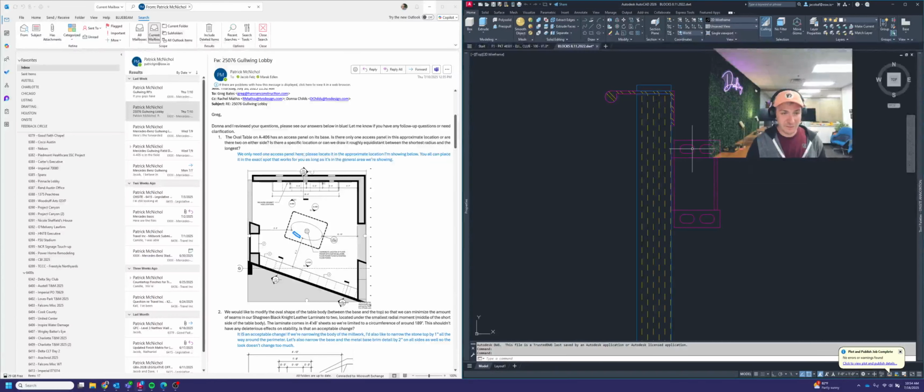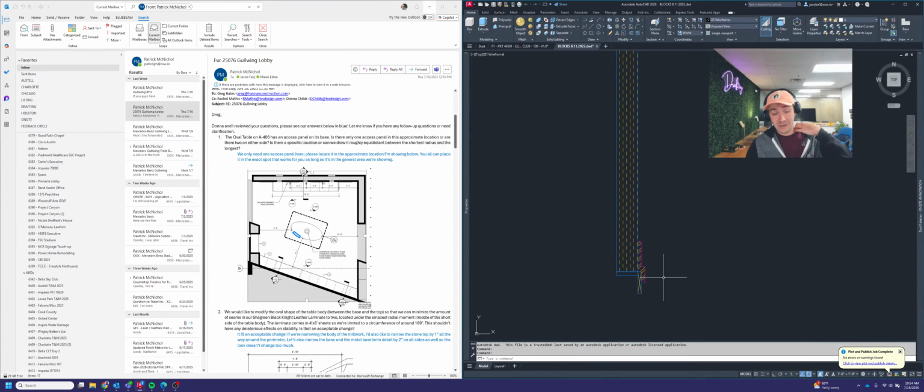So that's holding the panel on at the top. At the bottom of your panel, we usually will use half of a Monarch Z clip. We use the top half of a Monarch Z clip to attach that to a piece of blocking that sits at the bottom. So if you see one of these out in the shop or in our shop here, 9 times out of 10 you'll see the construction of an access panel looking like this. They're kind of hard to see. If you look at a desk or something, you may see one, but it may be hard to see the hardware unless the back of the wall is unfinished. Then you might be able to see in there.